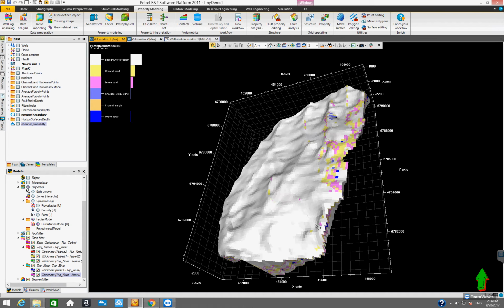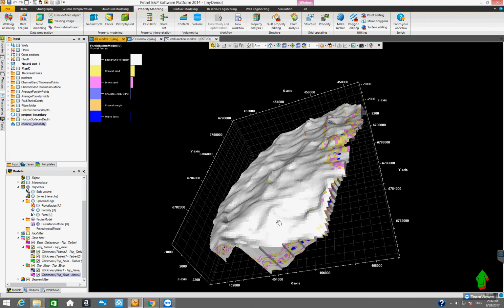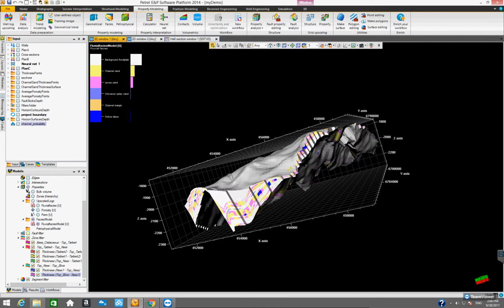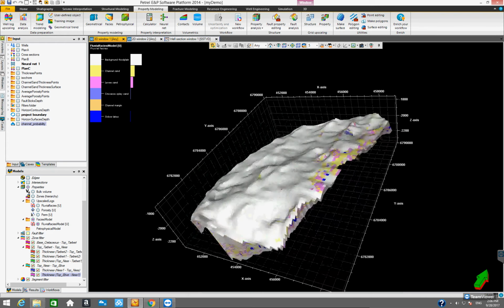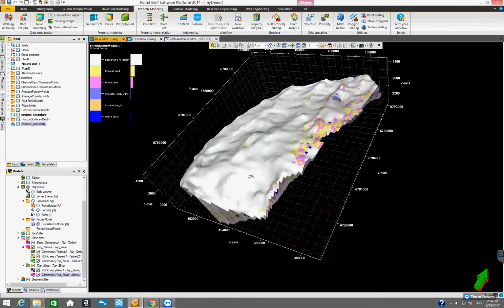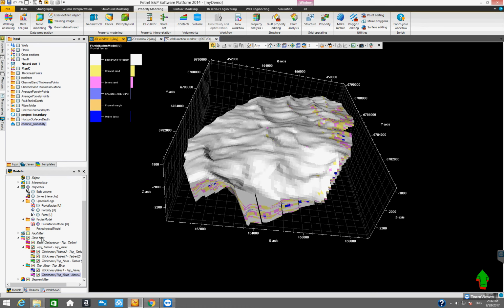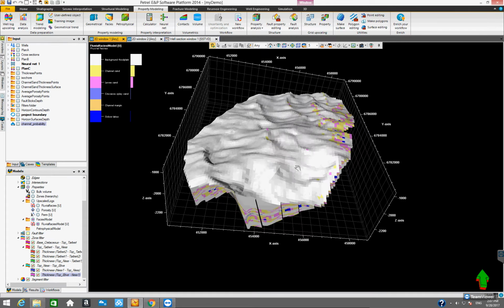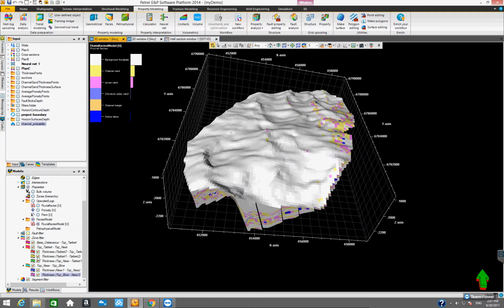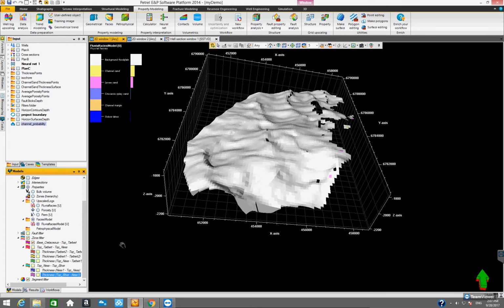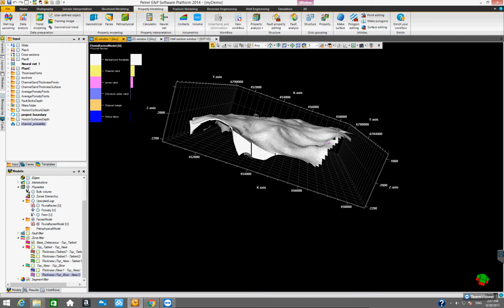And once our entire mesh is populated with this property, we may want to examine it and see if it indeed makes sense. The easiest way is probably just to use the zone filter and look at the property for every zone, right?